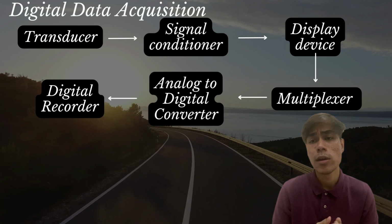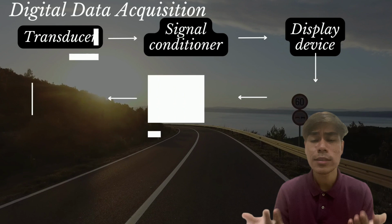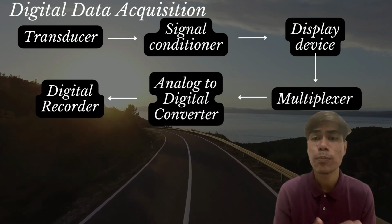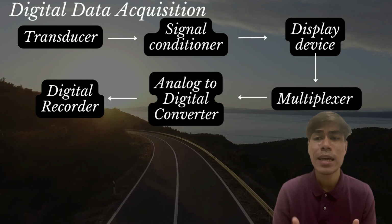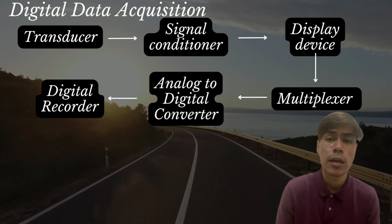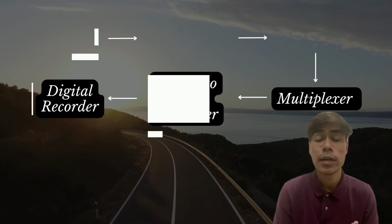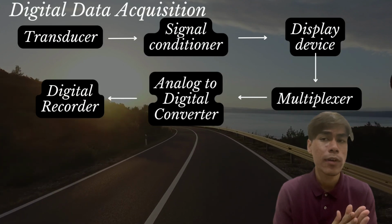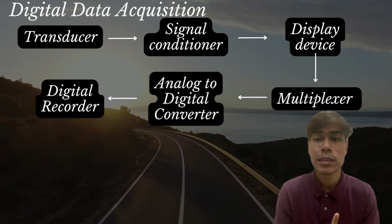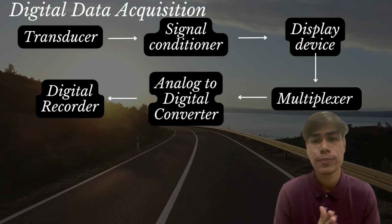The difference from analog is that digital has a multiplexer. What is a multiplexer? A multiplexer connects one of the multiple inputs to the output, so it acts as a parallel to serial converter. And then, digital needs an analog to digital converter. It converts the analog input into its equivalent digital output. Thirdly, a digital recorder is used to record the data in digital format.